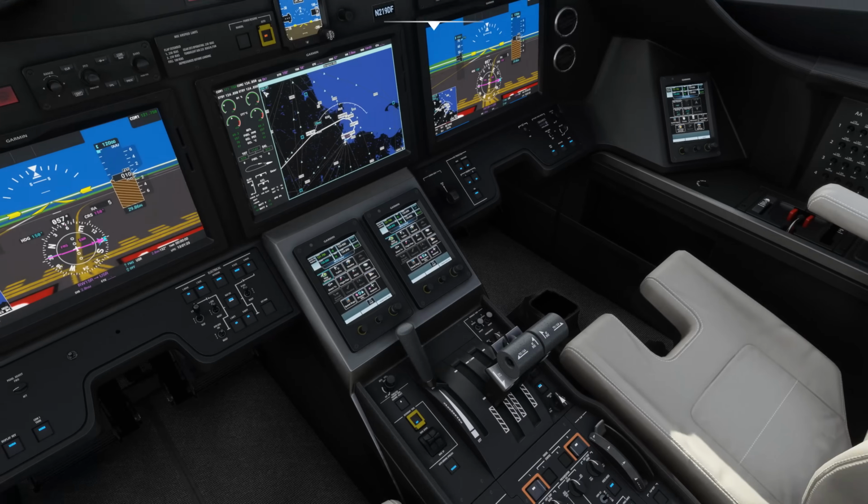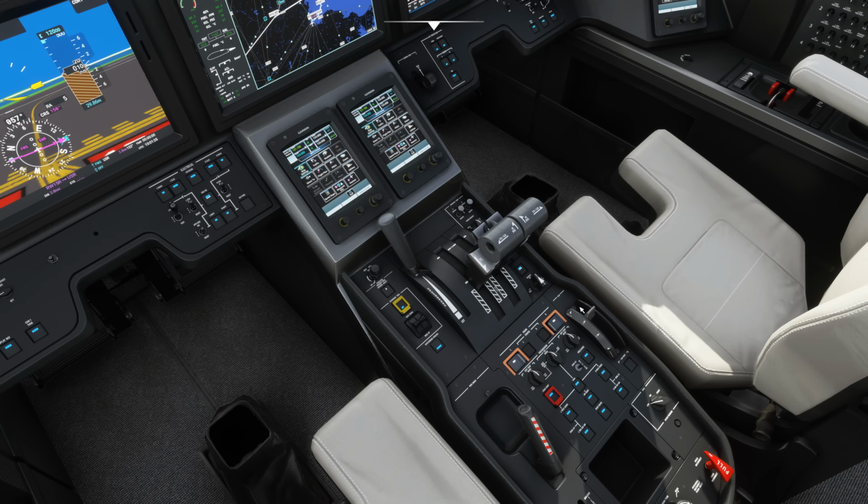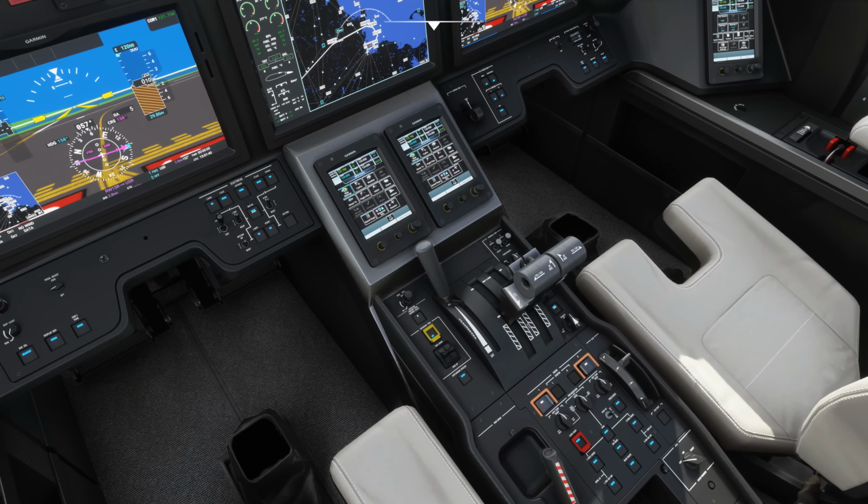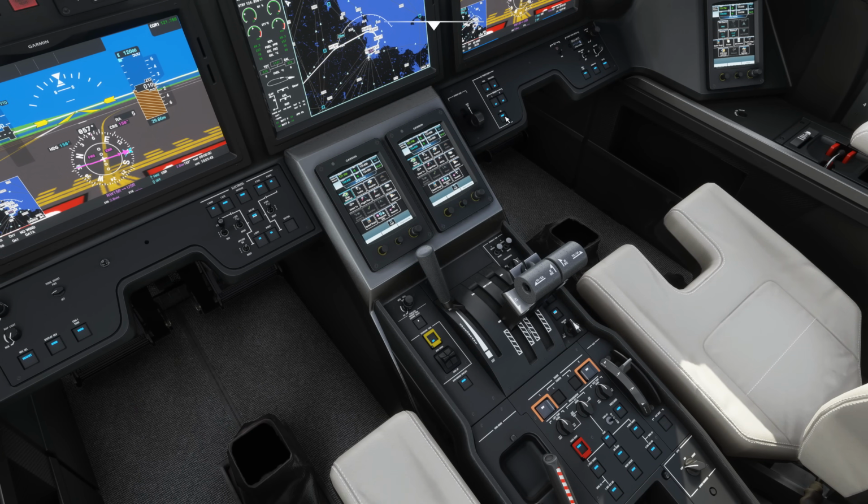So, actually, flaps, we need to set those. Flaps 1 for takeoff is what we're going to be using for today's flight, according to our chart. Speed brakes are retracted. Auto spoilers or ground spoilers armed in the event of a rejected takeoff. Trim, remember we already set that to -4.5 degrees, so nose down 4.5 degrees. Anti-ice, we won't be needing it today, at least at this point.